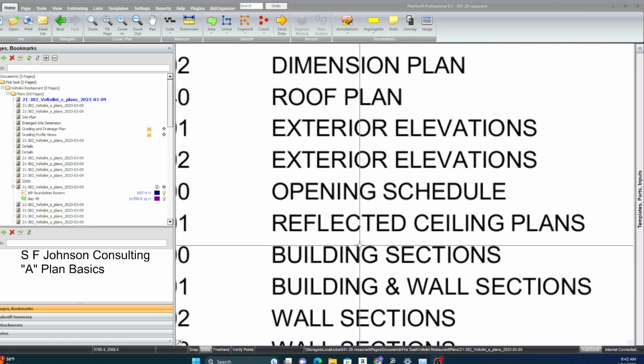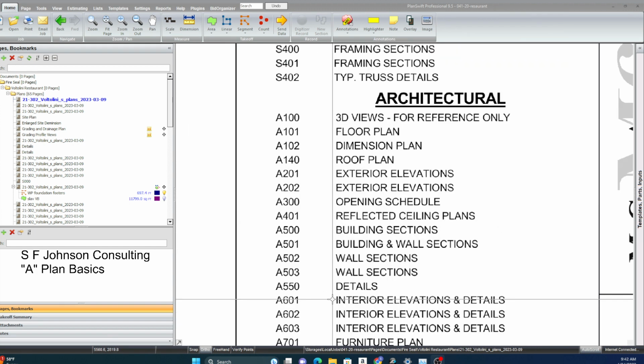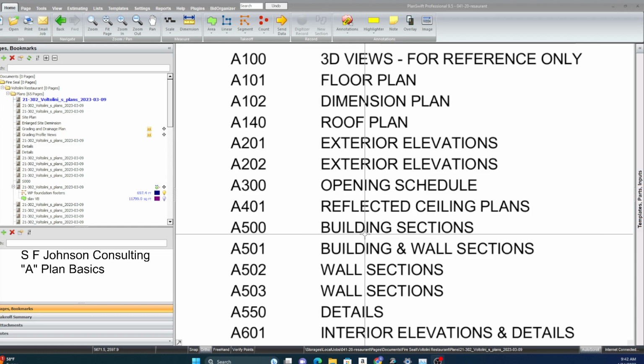And remember, in the architectural set we're talking about all finishes. Finishes is its own specification. So we go to the finishes, and we can find paint, we can find drywall even in the finishes specification. Everything here will be in that, but roofing will be in the thermal moisture specification.